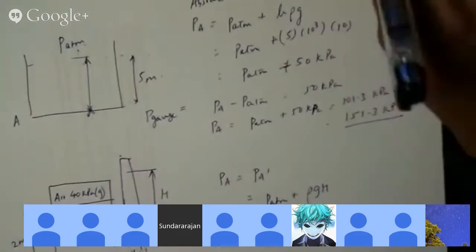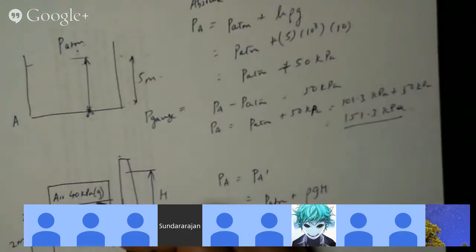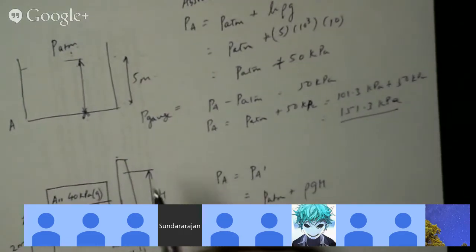Yeah, but it's not just 40 kilopascals because this is gauge pressure. So if you want the actual pressure, it should be P atmospheric plus 40 kilopascals plus rho GH plus rho G times 2. That's why it's gauge. So you need to add the atmospheric pressure for this.